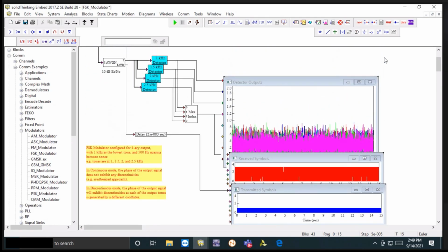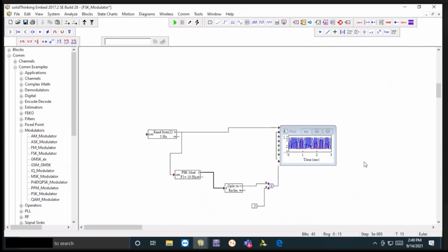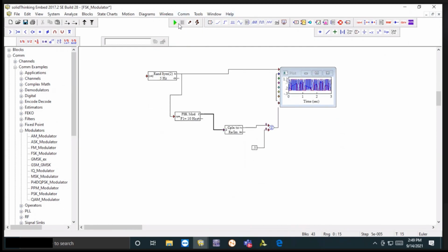And to extract this, what do we have to do, how to extract the master signal back from this? So you can see that actually we have the variation in the frequency, right? So if you want to extract the signal, obviously you should use the bandpass filter for frequency modulation, or for FSK also. The decisions should be on the basis of the band pass filter.